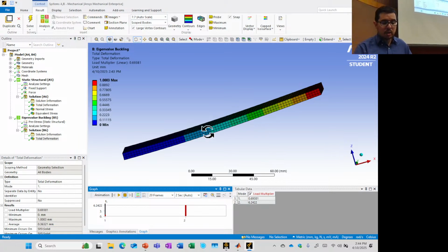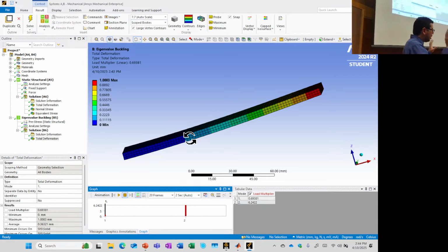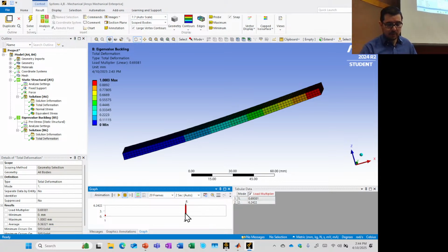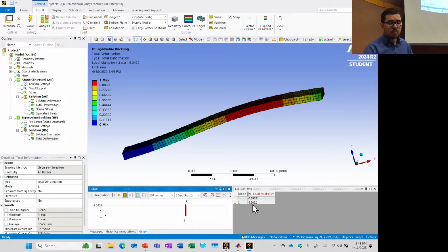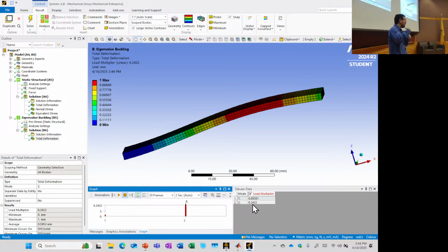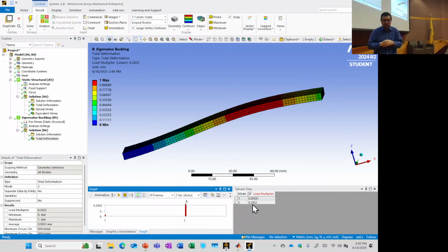So we're kind of done. We're pseudo done. And to get to the second mode, we would have to multiply by 6. So at 60 kilonewtons, you could get this second mode. It's kind of a moot point, though, right? You will have already failed by mode 1 with this 10 kilonewtons. It will just simulate things. It will tell you interesting ideas and give you this information, but it's creating a pretty picture. We have to use some of our intuition.